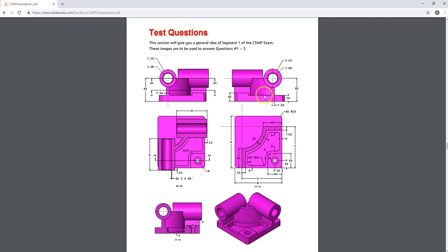Here's the front view, here's the right side. These three views here, here, and here are section views, and you can see the cutting plane lines that dictate what's shown. Let's look at HH. Here's HH through HH, and you'll notice that there's a cutting plane line, HH through HH, and notice the arrows are pointing down. What that means is anything behind it has been cut off. And so we're looking from the top down on this part, removing this top. And you can see right here that everywhere that there was solid material that's been cut by the cutting plane has section lines, and that's what those lines mean.